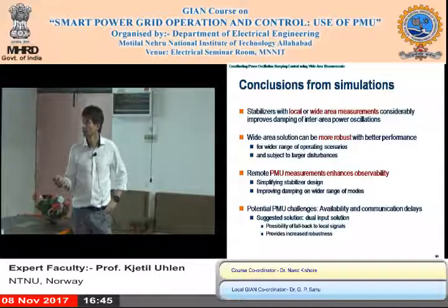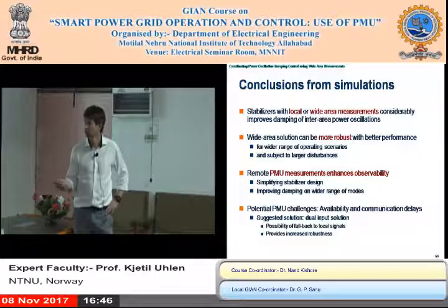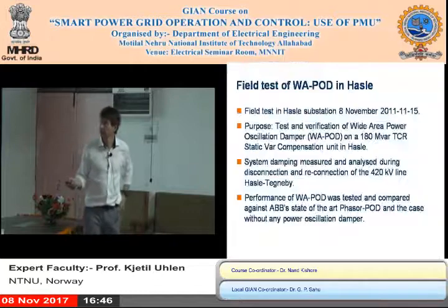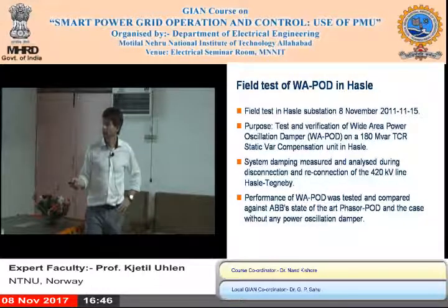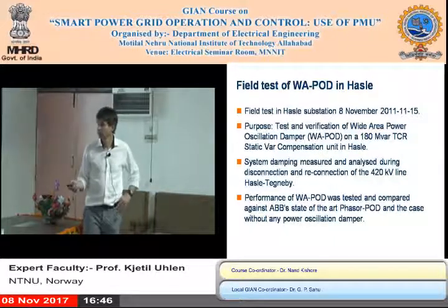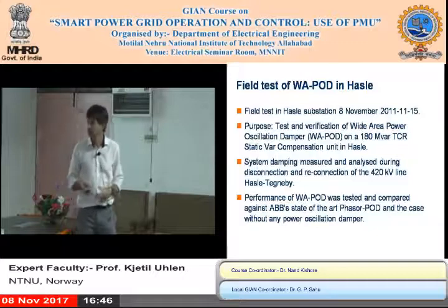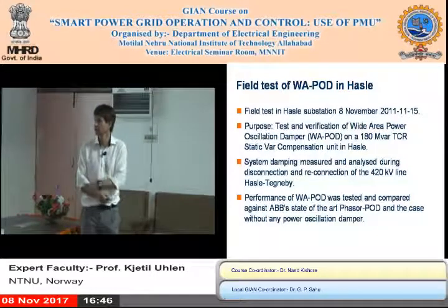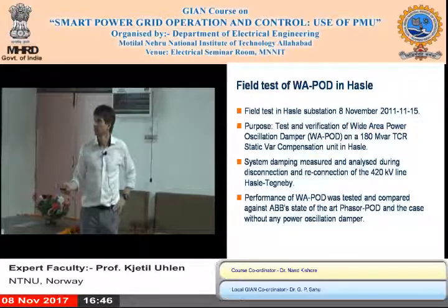So some years ago we did a field test on that at the substation. We tested the wide area power oscillation damper that we had designed on a 180 megawatt thyristor controlled reactor. So it's an SVC unit, but only with thyristor controlled reactors combined with a capacitor bank, so it worked as an SVC.